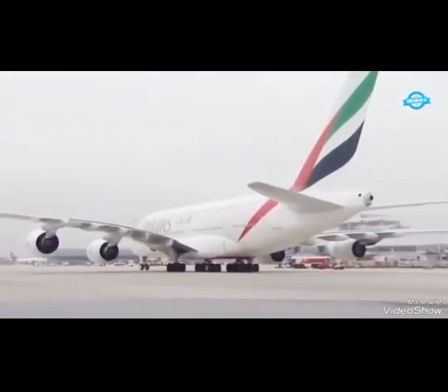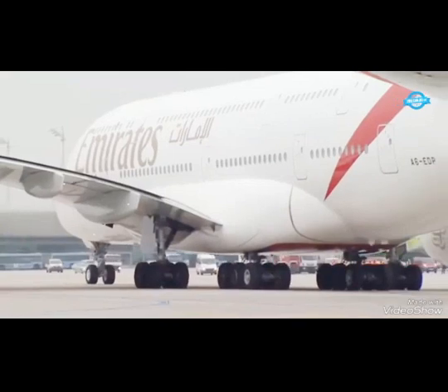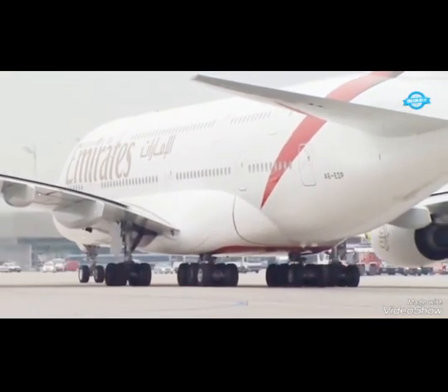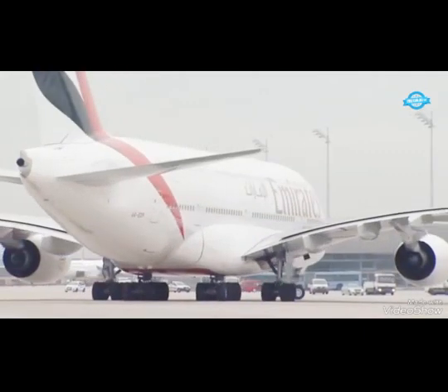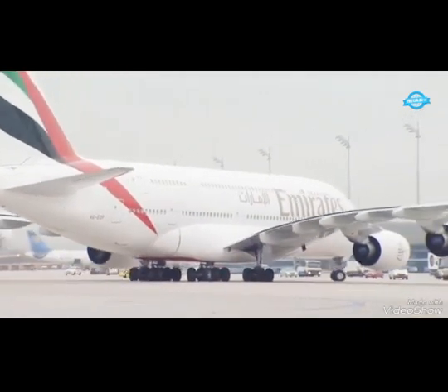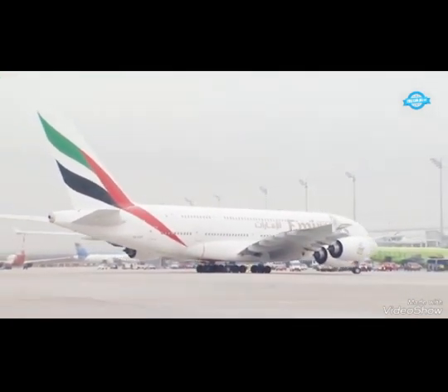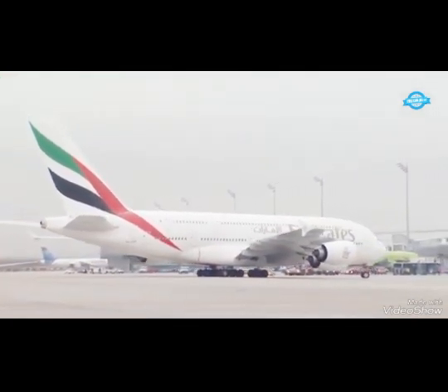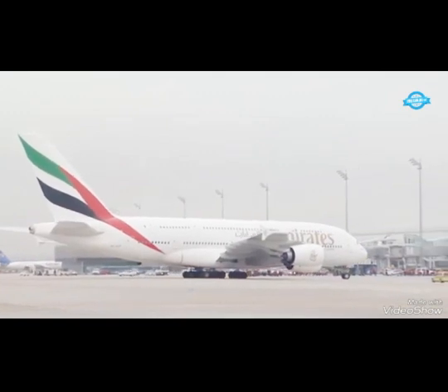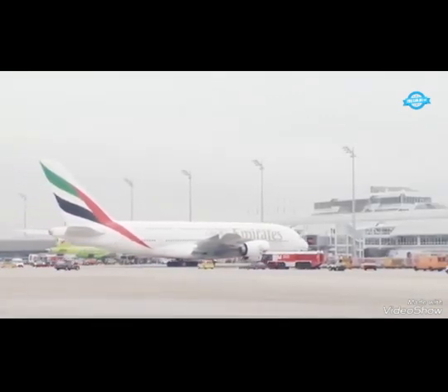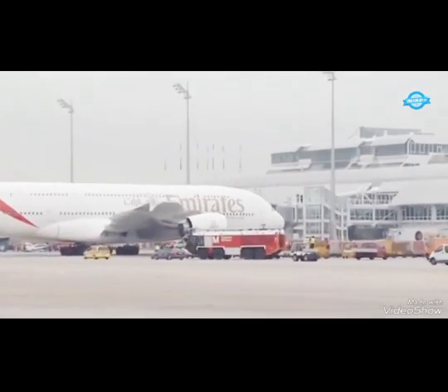One interesting feature of the A380's design is the use of thrust reversers, which are only equipped on the two inboard engines. This decision was made to save weight and protect the outboard engines, which occasionally extend beyond the edges of the runway and are more susceptible to foreign object damage. The thrust reversers can only be activated on the ground and provide pilots with varying degrees of reverse thrust until the aircraft slows to speeds below 70 knots.